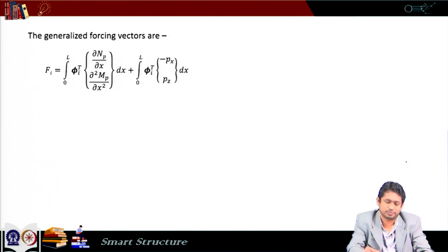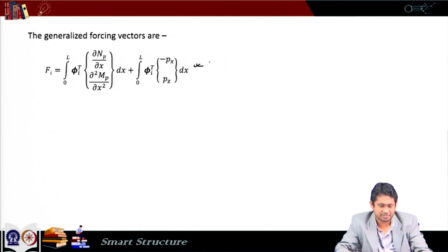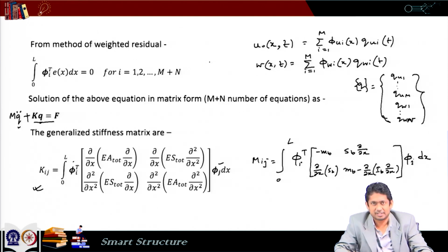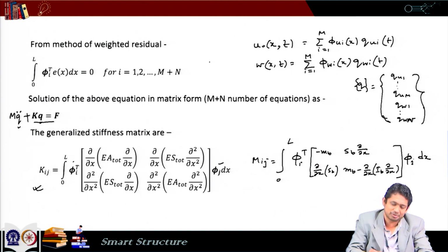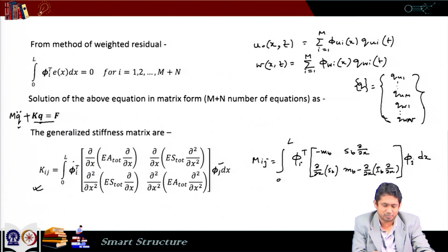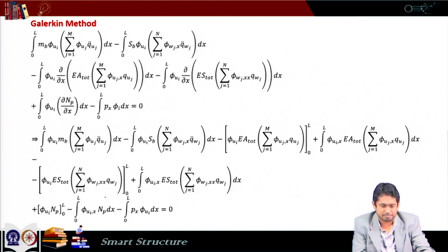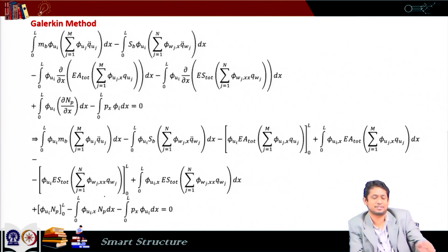Force we already know, we did it while solving the static problem. So, this completes the first approach. Again, here we did not shift the derivatives using integration by parts. So, because of this, while we approximate our phi, we have to make sure that these derivatives all exist for phi. Now, in the second approach, we will shift these derivatives. In that case, the requirement on the order of differentiation would be less.